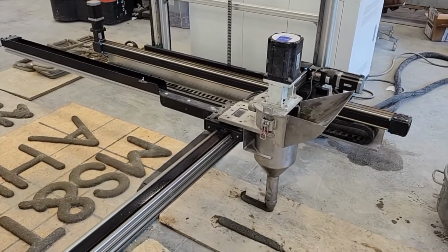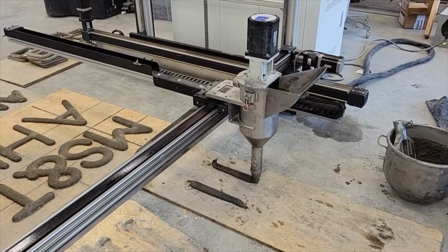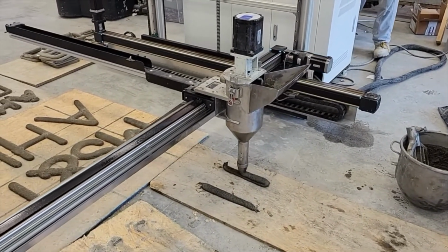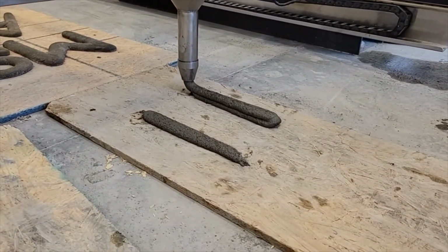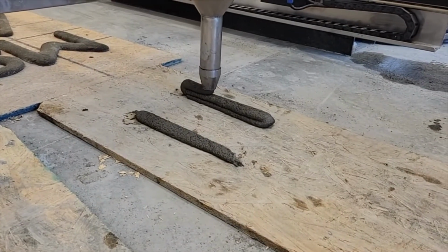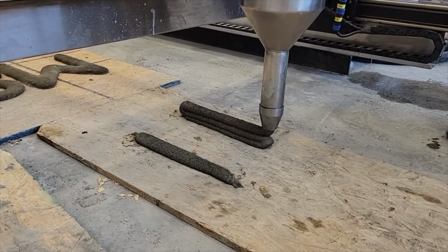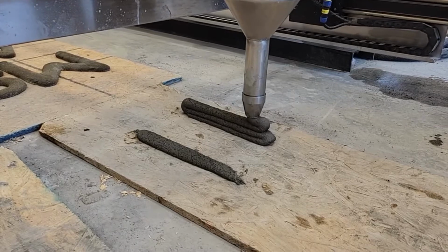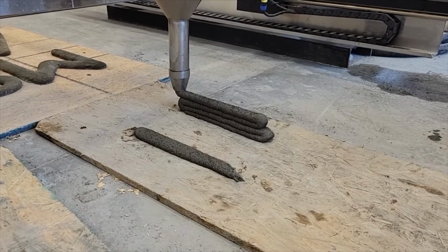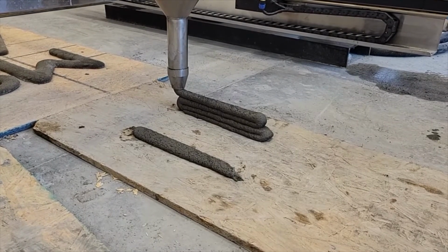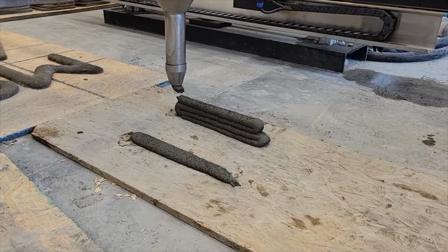Another important lesson that I should highlight is that evaluating extrudability only based on energy or force tests may not give us a complete picture of the extrusion process. Filament inspection tests, which evaluate the quality of the deposited filament, can provide a better understanding of the process. Qualitative assessment involves examining the ability of the printing material to be continuously extruded and the quality of the extruded filament. Combining the quantitative extrusion energy test with the qualitative filament inspection method is a useful technique for evaluating extrudability.